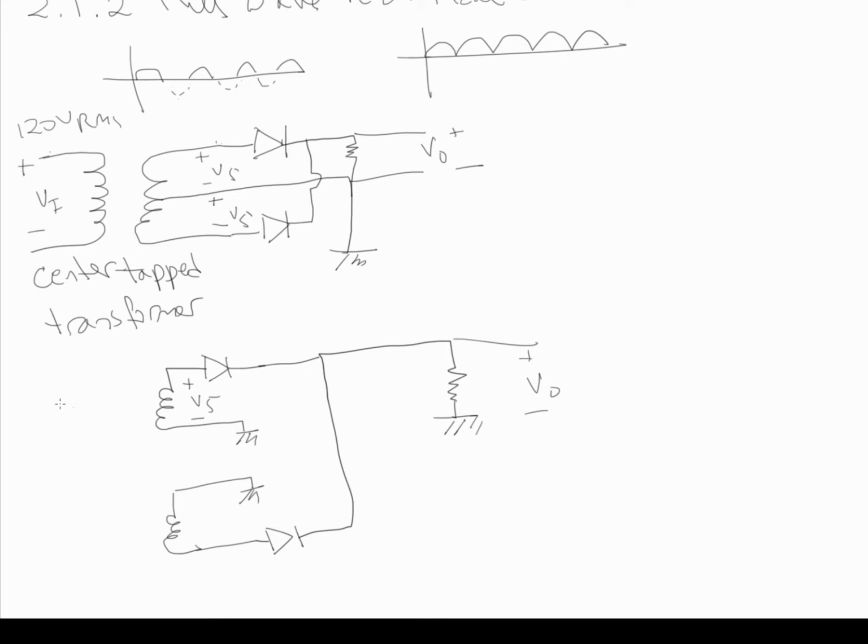So you can see, if I draw an input signal and it's positive, this is our Vs, plus minus Vs. Then anytime we're over V gamma, this is plus minus V gamma, our diode is going to conduct and we get a peak.